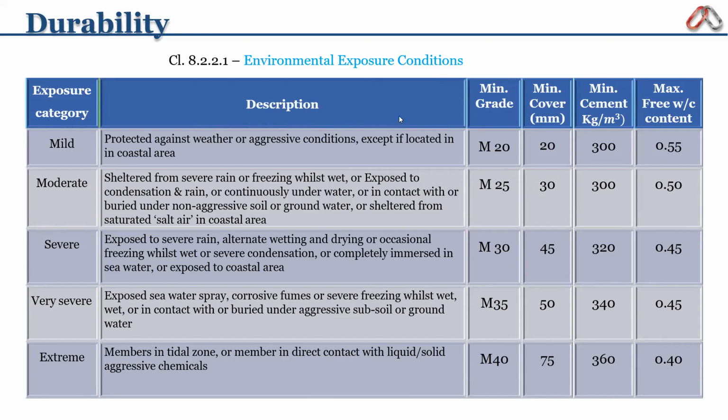Then if M25 grade is given, you can use the clear cover of 50, and the exposure category is very, very severe. And if M40 grade of concrete is there, you can use the minimum clear cover of 75. But mostly in design, the grades that you are going to use are M20 to M30. M35 or M40 is very rarely used in designing. So this is how the durability of concrete depends upon the grade of the concrete.